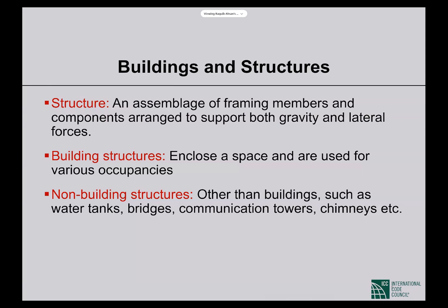That makes it a building, and the structure of a building is a building structure. Non-building structures are structures other than buildings, such as water tanks, bridges, communication towers, chimneys, etc. Now, are non-building structures covered in the building code? Yes and no. For example, even for the design of non-building structures, we use the building code to determine load.